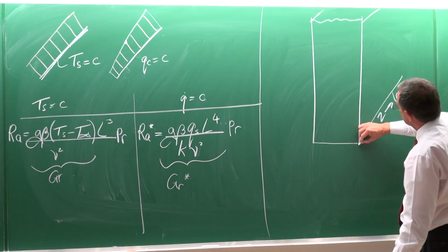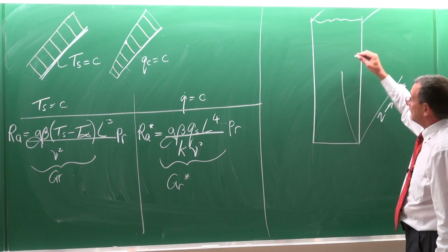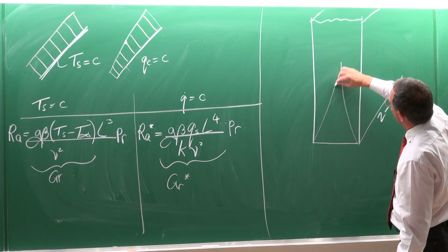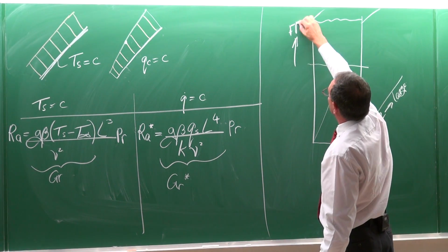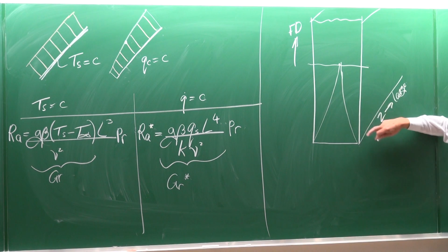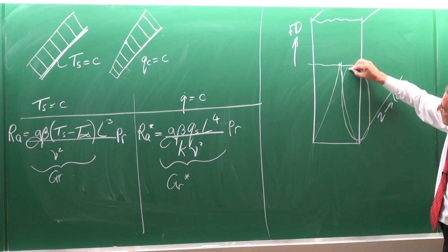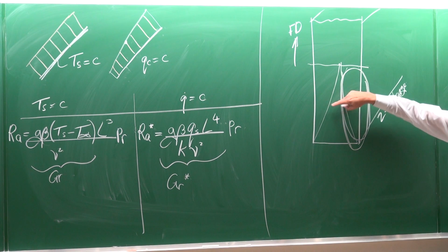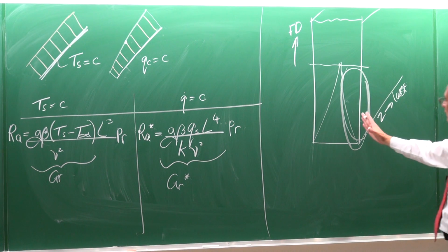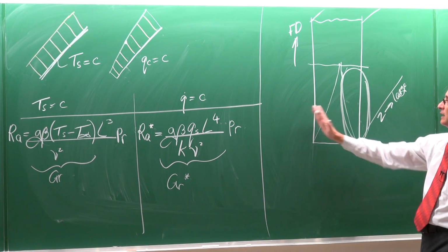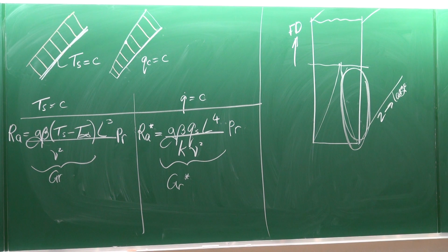What they're going to do is they're going to have the thermal boundary layer that's going to grow up to that point there. And from there on, we know we've got fully developed flow. But in this region here, this boundary layer is not being influenced by the other boundary layer. So this is a flat plate situation. You see? Just by considering a flat plate, you can get the heat transfer rate from this one and from that one, and you can do your calculations. So remember, small things like this are very important.